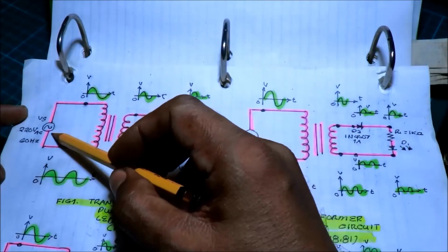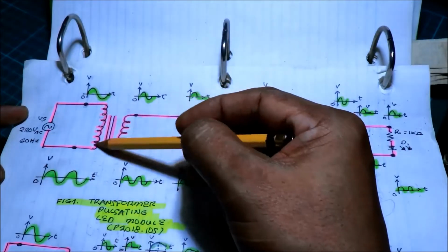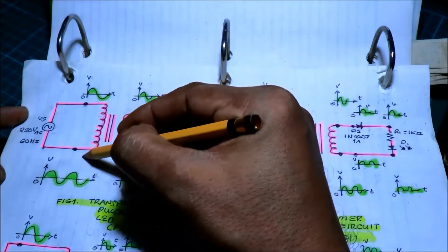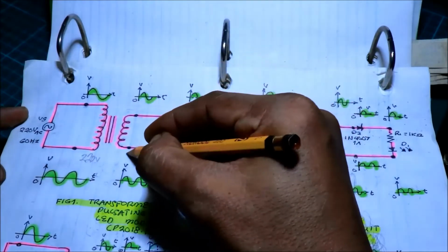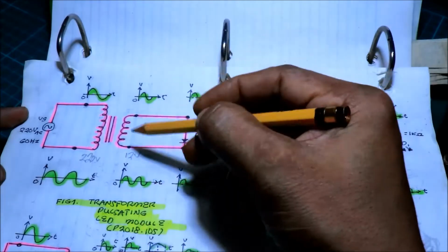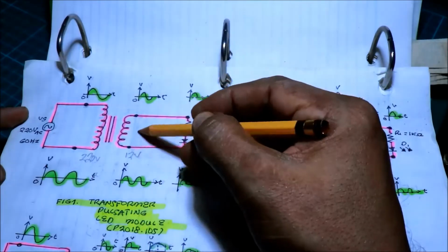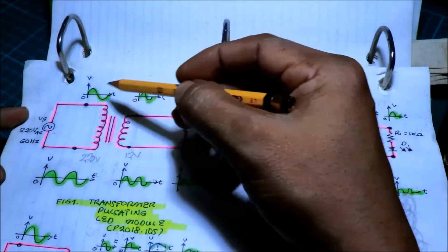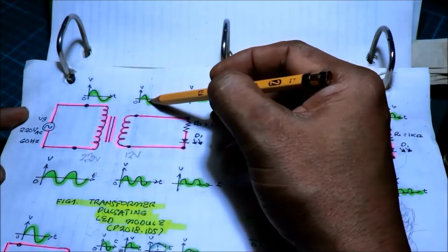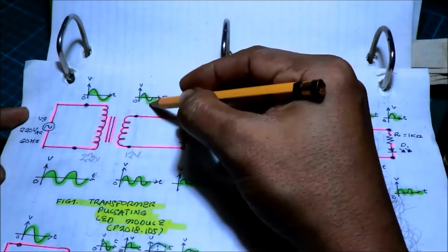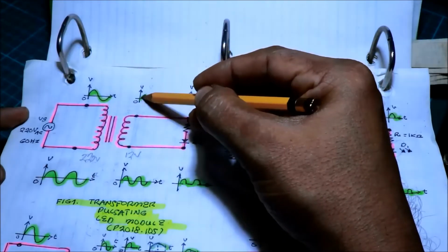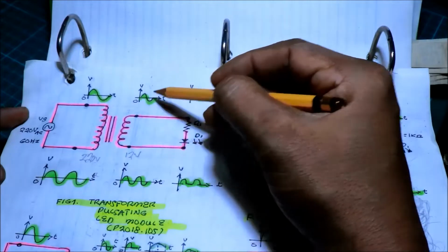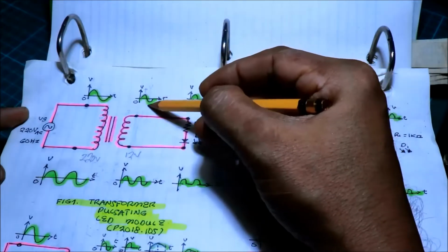This is the primary side of the transformer, 220 volts, and then the step down transformer becomes 12 volts. This is now the secondary windings, from 220 to 12 volts. A big sine wave becomes a smaller sine wave. This 12 volts small sine wave has 2 components: the first half cycle and second half cycle, the positive half cycle and negative half cycle.